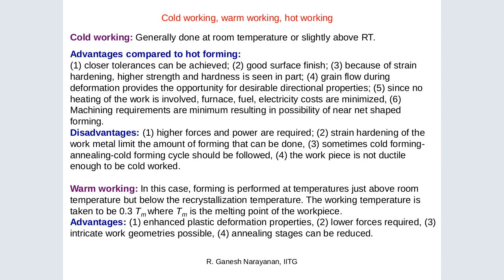It has a good surface finish because of strain hardening. It has a higher strength and hardness. And number 4, the grain flow during deformation provides the opportunity for desirable directional properties.